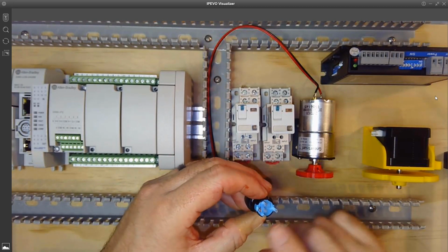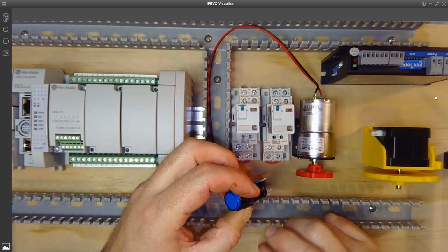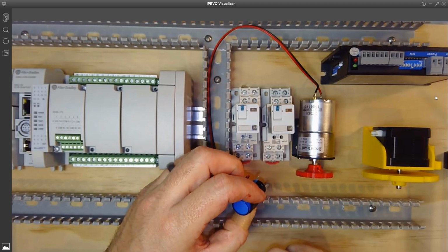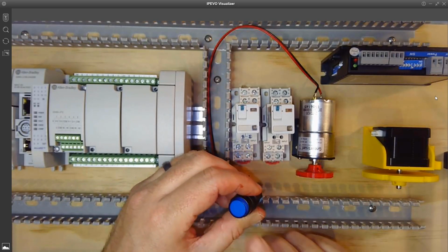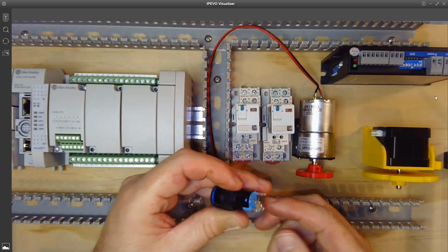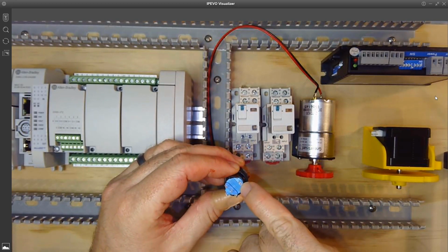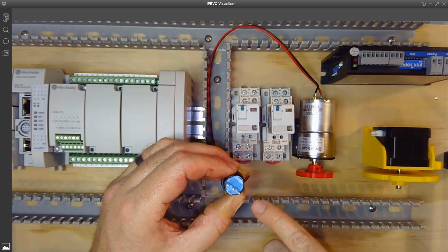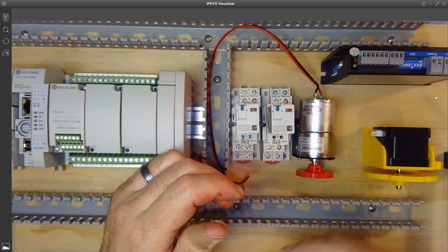And then you'll see there's two more terminals, and that's for the illuminated part. So these are kind of nice push buttons in that the illumination is independent of the press of the button. It's not that it turns on when you press the button, the lamp turns on when you put voltage on these upper and lower pins. And when you get yours and see them, you'll see that this pin down here, the furthest one away, is marked negative, and this one up on top is marked positive. So keep that in mind. That's one of the devices you're going to be using.